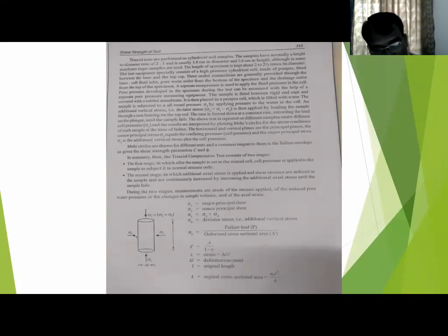So when we performed the direct shear test, there it wasn't there. We didn't have to measure the pore water pressure separately, but in triaxial test you can measure the pore water pressure separately. That is the biggest advantage here. There what we used to take, टोटल स्ट्रेस ही हम लेके करते थे, पोर वाटर प्रेशर हमारे पास सेपरेट नहीं था। तो डायरेक्ट में और ट्रायक्सियल में ये सबसे मेजर डिफरेंस है। I hope things are clear to you now.